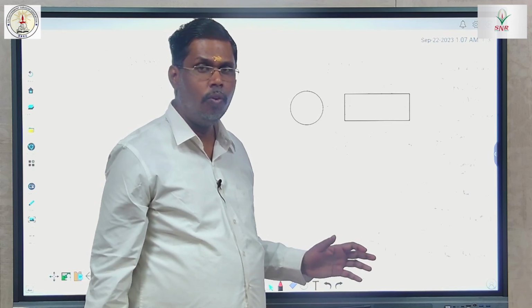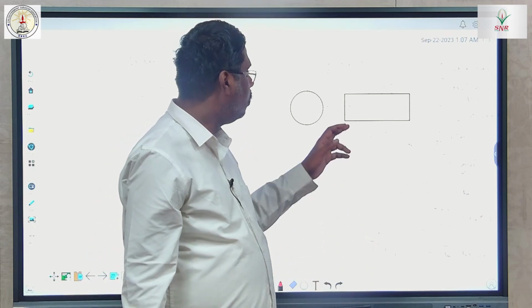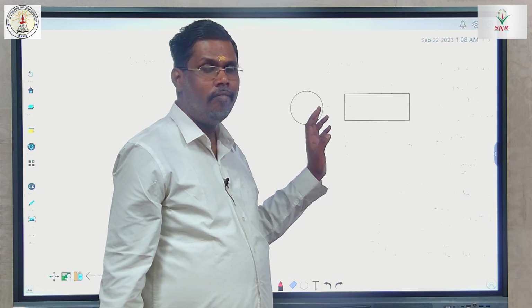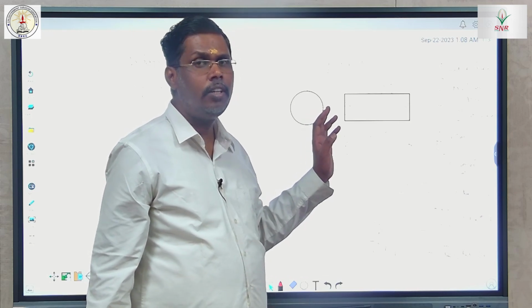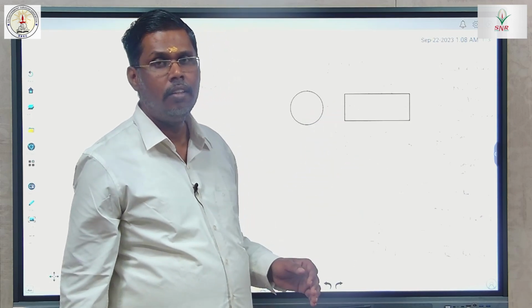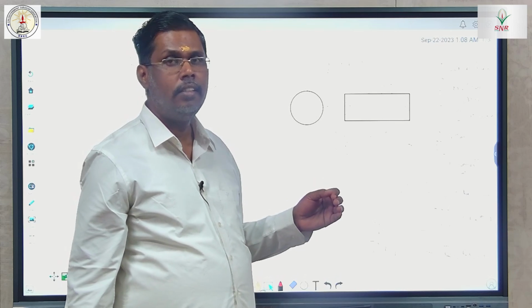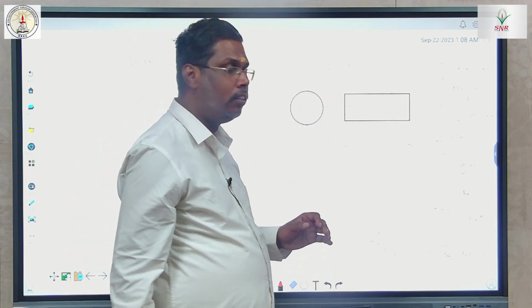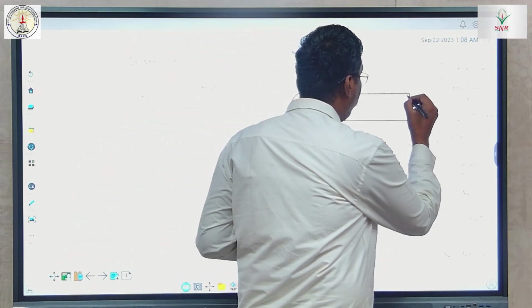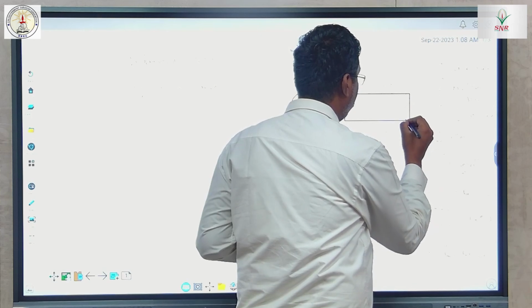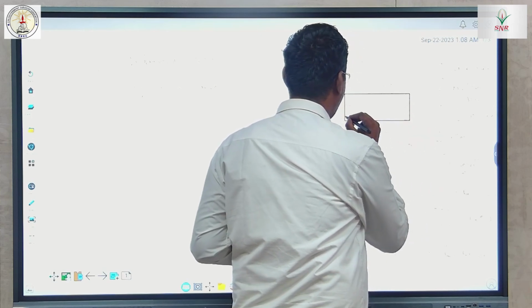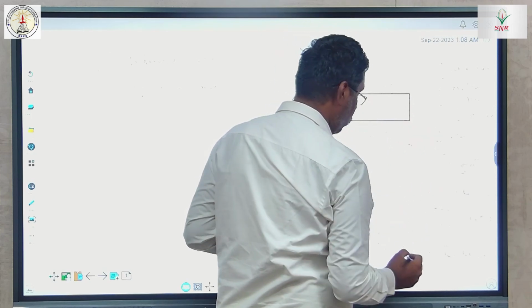I will definitely say no. So it should not get damaged. What provision do you have to make? Yes, that is nothing but your chamfer. You have to give a chamfer over here, right?